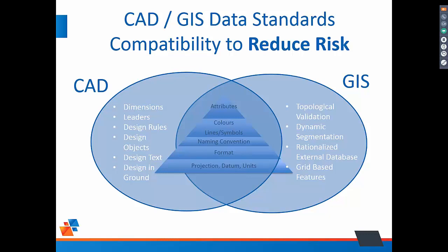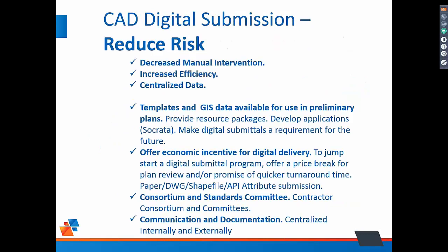But because it's all used in a life cycle for any project to manage our data, it's really important that we identify where those two data sets are compatible and ease that transition through knowing what the dependencies and the commonalities are for each. In identifying those, that is how you can create CAD features that are compatible with GIS objects.